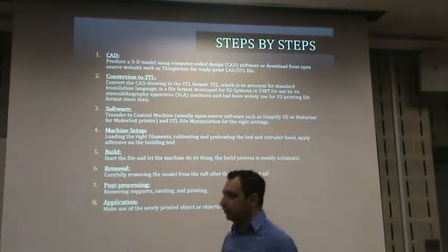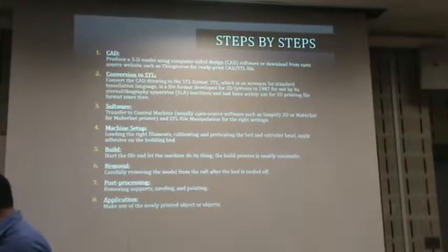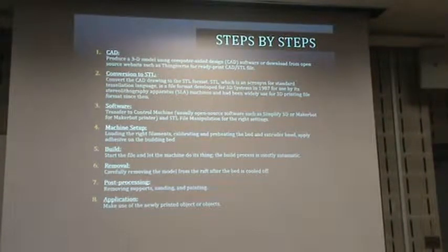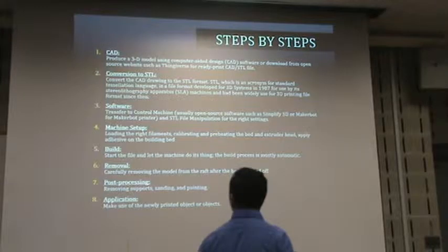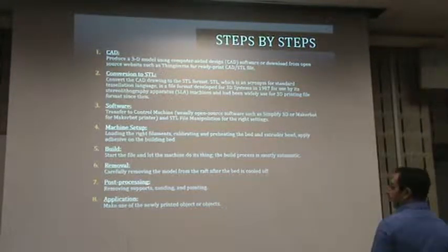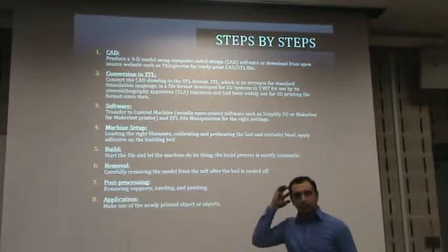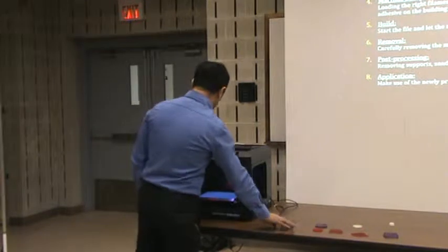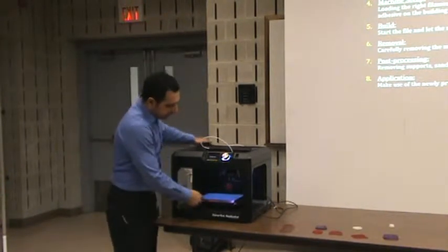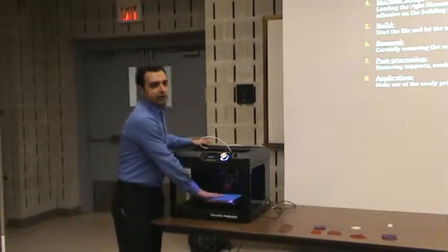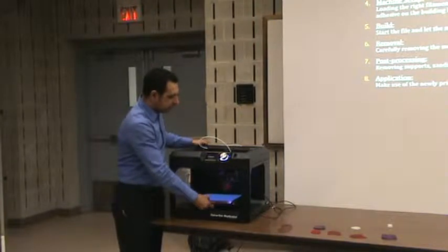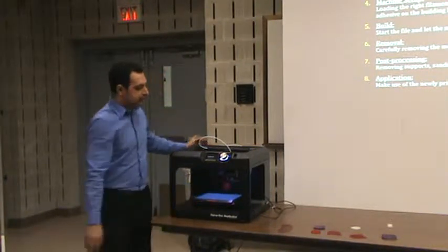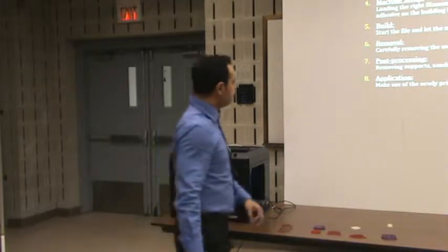This will give you the progress, how much percent it's over. I wish it started up earlier. I could actually demo something. And then after it's over, let it cool down because when it's hot, you don't want to touch it. And once it's cooled down, then you can use a scraper. We have scrapers to take that off, but make sure that you don't pull off the model while the plate is in the machine. You have to take the plate out and then take the piece that you have printed.